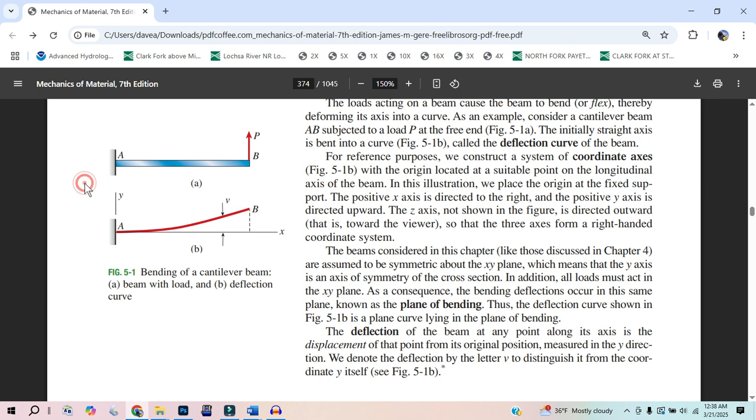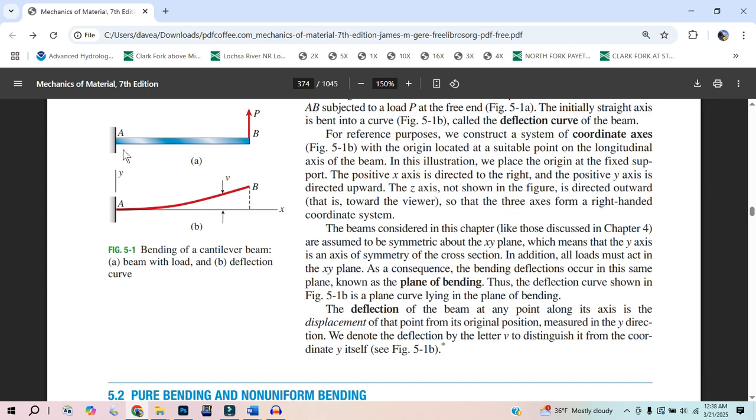That wasn't a very good explanation, but your shear force is associated with your moment, because when you know your shear force diagram and you integrate it, you get the moment diagram.